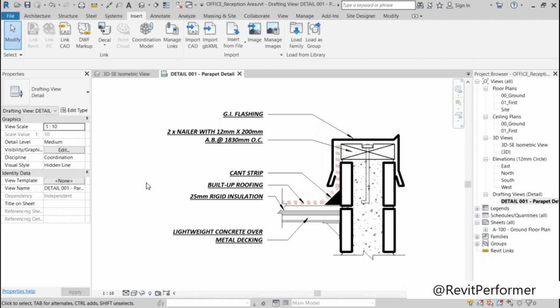Now, you wouldn't just do it piece by piece like I've done here. What you would do is create a Revit template with all the same standard settings as you may have in your AutoCAD drawings that you're also utilizing to develop your Revit project. But you can see how quick and easy it is to do. It's not difficult. You just have to have a different workflow process and utilize your family types in your system families in Revit.